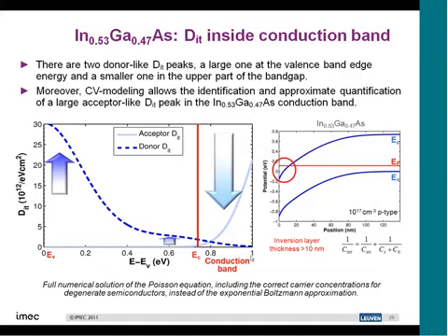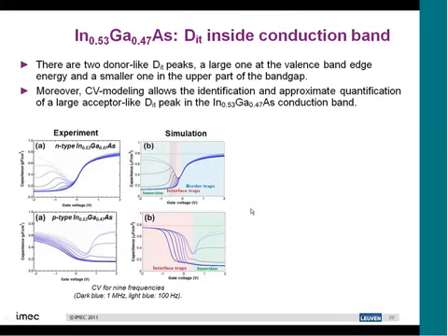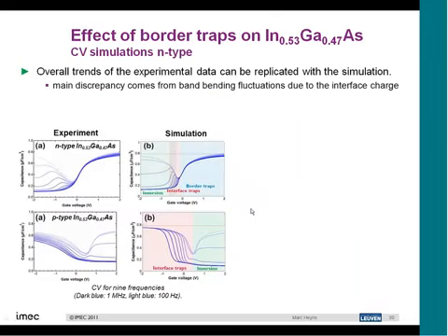layer. Here, the Fermi level really moves inside the conduction band, which means that also the defects and everything happening actually at the bottom of the conduction band also becomes important. So that's another complication. Moreover, due to the fact that we have materials here with a low effective mass, it means that these carriers will also tunnel into the oxide much easier, and you will have much more interaction with what we call border traps.